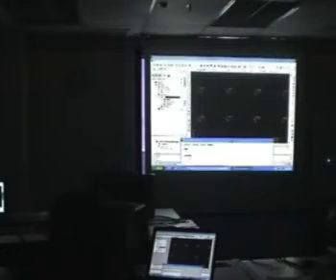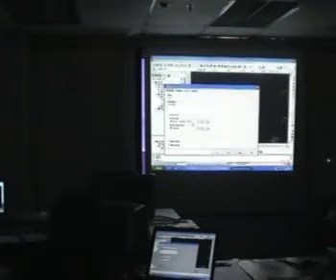So it's lighter in the sense that you don't have to load them into the drawing. You don't have to erase them, switch out the layers, none of that. You just need to play around with surface styles. And these surface styles you can create your own as well if you want to be very specific. Instead of a 1 meter interval for contours, you want to set 5 meter intervals. You want to set different colors, different names of the layers for the contours. Everything is completely customizable in Civil 3D.